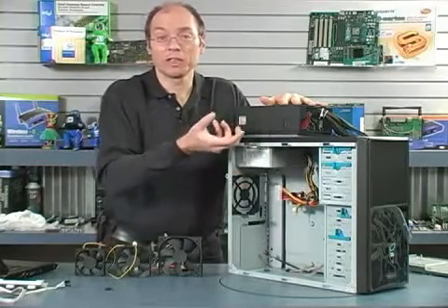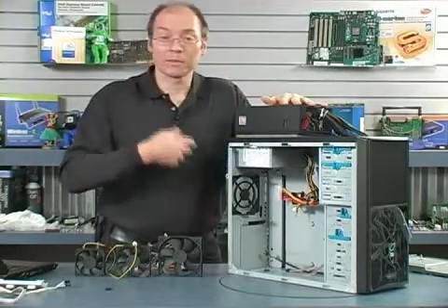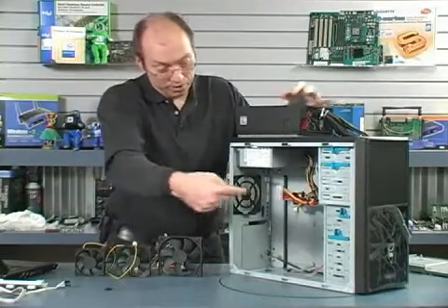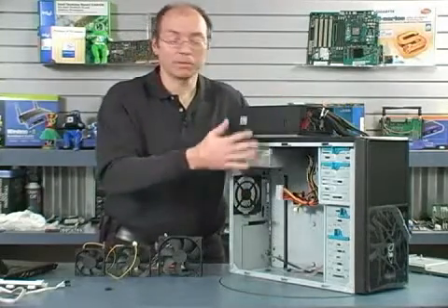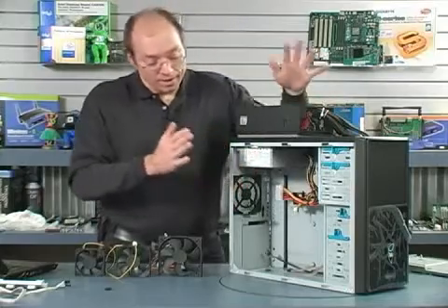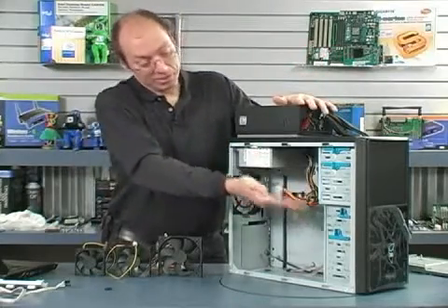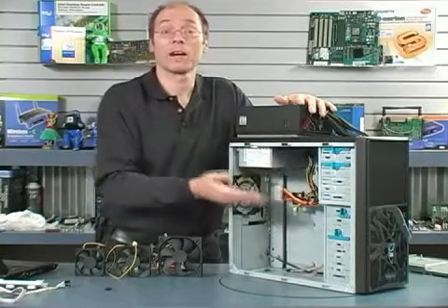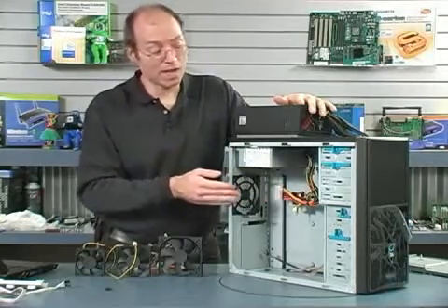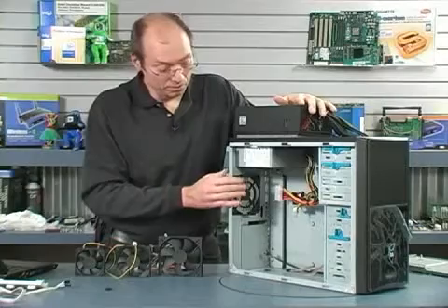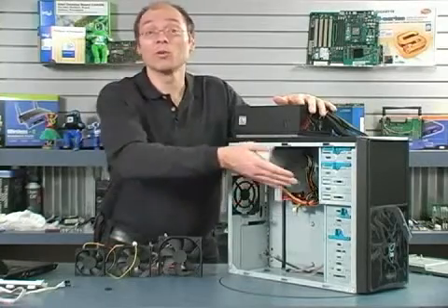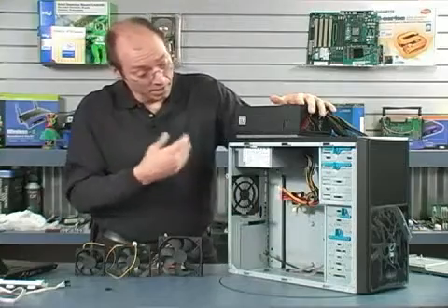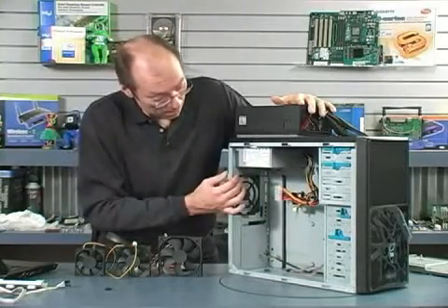They allow the drive to move a little bit, and you end up getting rattles and noise. And without the secure mounting, without screws going in through the case on either side, you lose a bit of rigidity too. So I used to like these kind of things, but anymore I take them out and discard them, and I mount all of the drives with screws. It does take a little bit more time, but I think you end up with a more securely mounted set of drives. The cooling is better because they're more directly attached to the metal of the case, and it just seems to work out better.